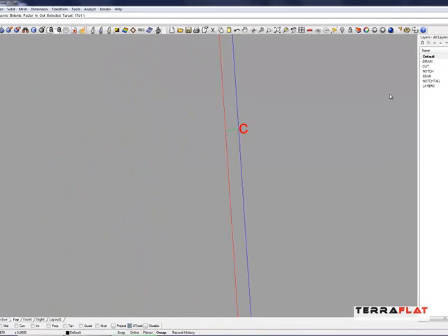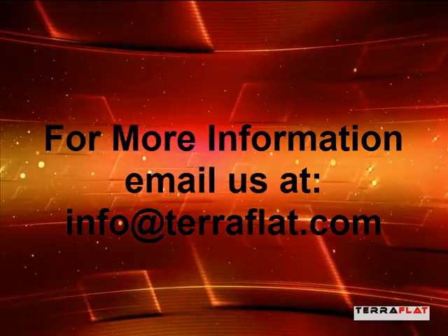Our notch tag information is all on this, and our original cut line is in blue. So our cut line's blue, and our seam allowance is red. The green tags are the notch, and we have the C that we added along with that notch piece. So this is, in essence, taking a 3D car seat model and going right through to flattening it, ready to export out to our plotter or our cutter.